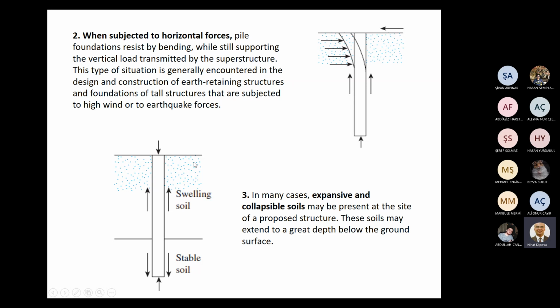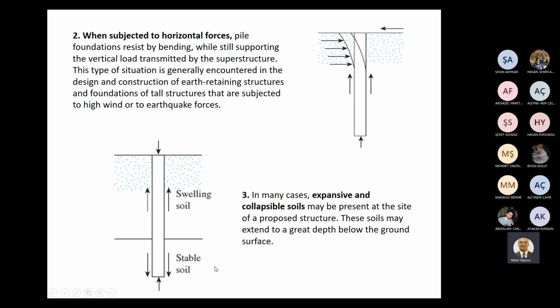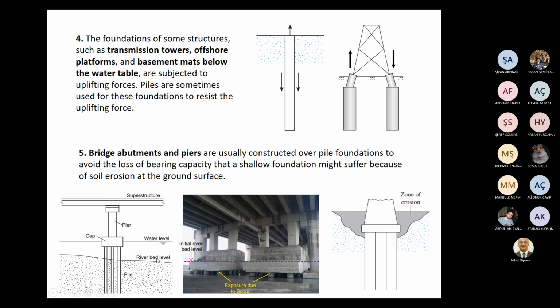So, because the bearing capacity is extremely low, the load of the superstructure should be transferred to stable soil below that by using pile foundation.